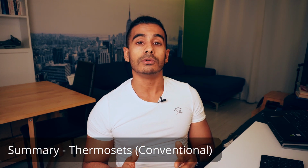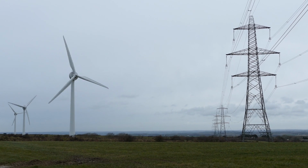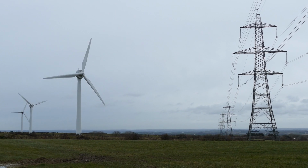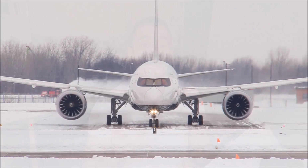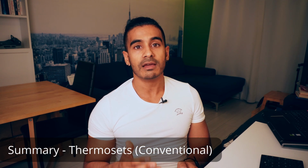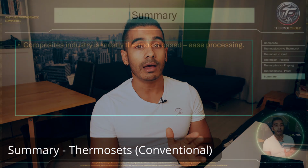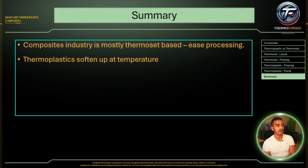If you want to use a thermoset at really high volume, say in the energy industry, aerospace and automotive and so on, the costs involved in scaling this up are very, very high in terms of processing costs. And that's where thermoplastic composite comes in.